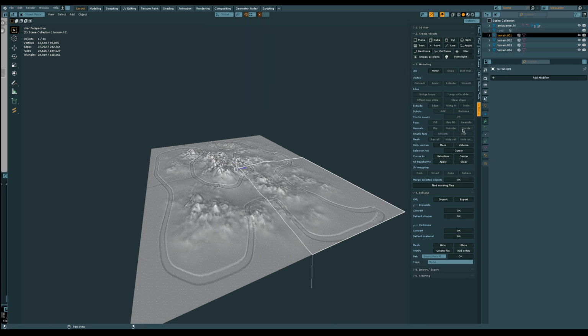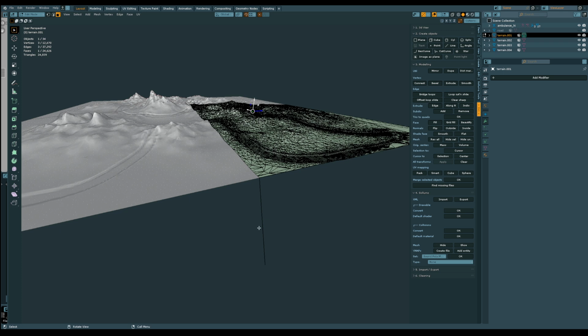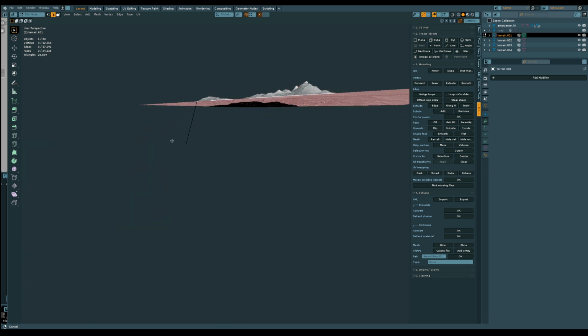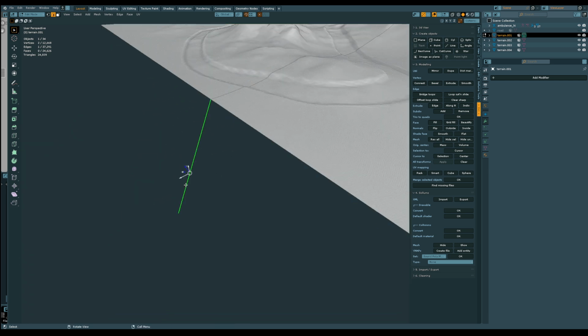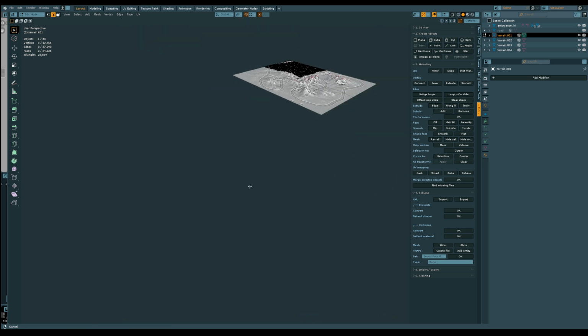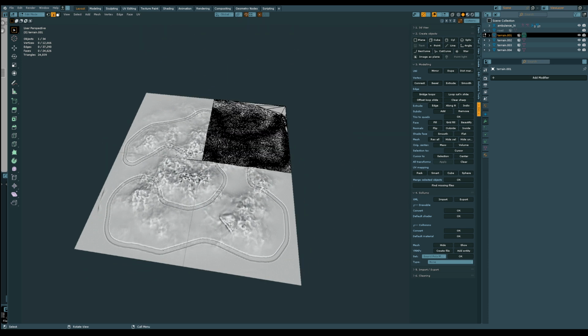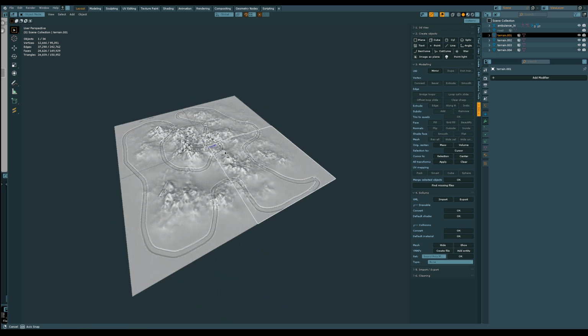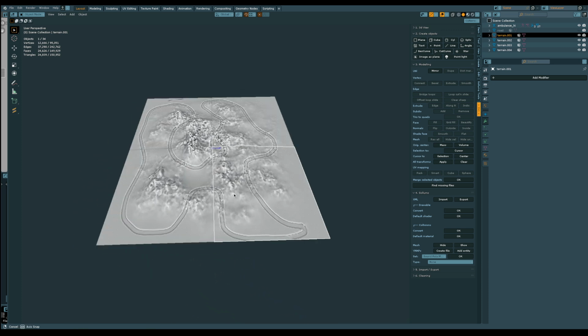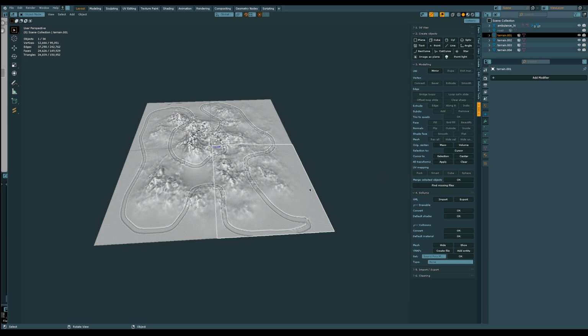And select the tile you want to edit in here, press number 2, select the edge, delete edge. I think I saw another one in here, right here. Delete edge. Alright, so let's center every single one of them and go to cursor, origin, center of mass.